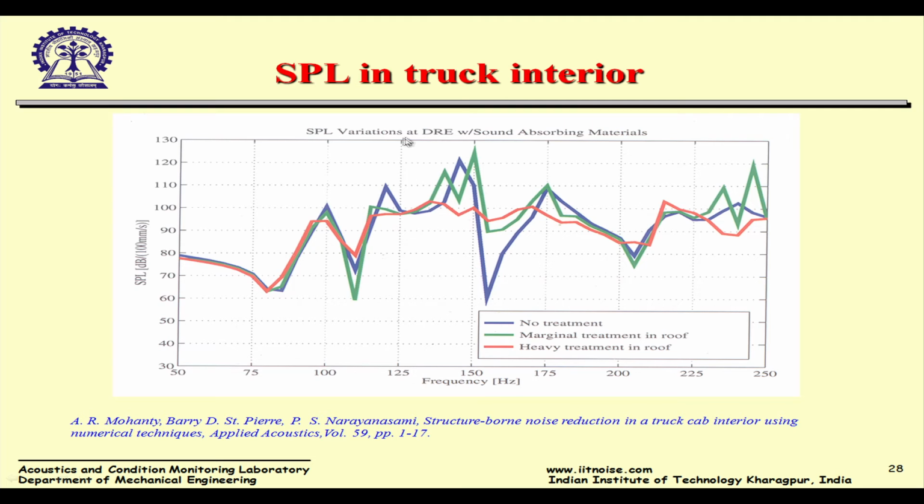And if you look at this final result of the SPL in the interior of the cab, where we have done a relative comparison with no treatment and two different types of treatment on the roof of the headliner of the cab, by heavy treatment I mean a high absorbing material. So I could bring down the overall noise in the driver's right ear location. So this is a procedure which we published 25 years ago, perhaps. So this is the technology today, and everybody for all plants are doing this in and out.